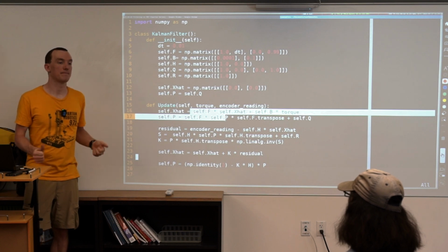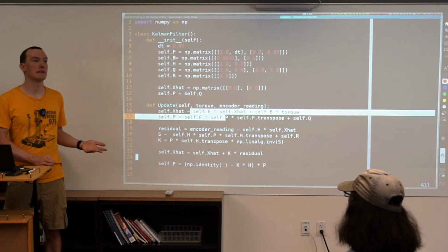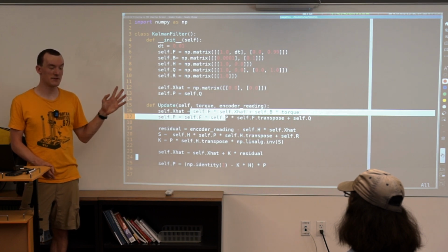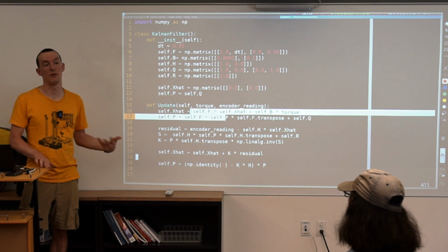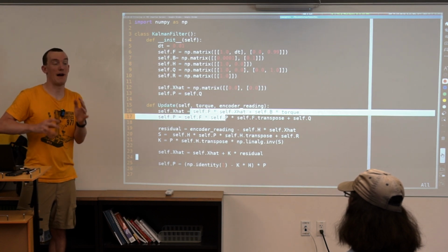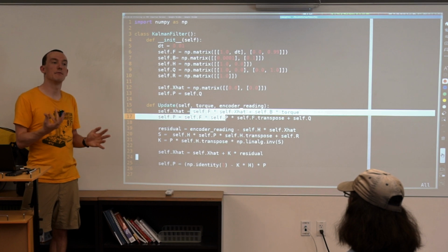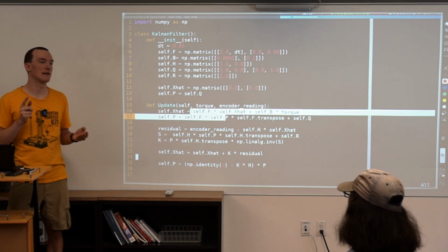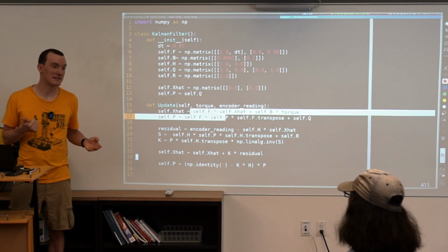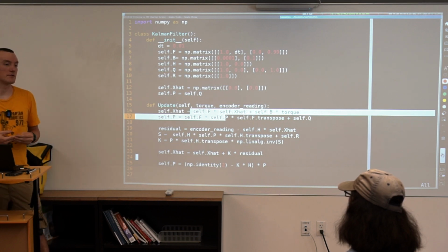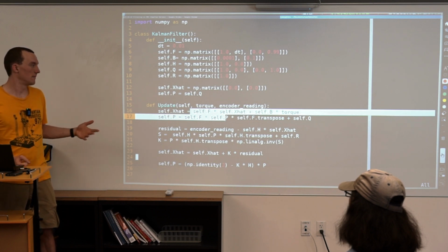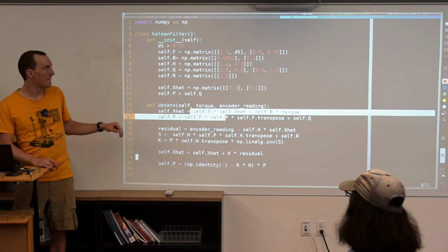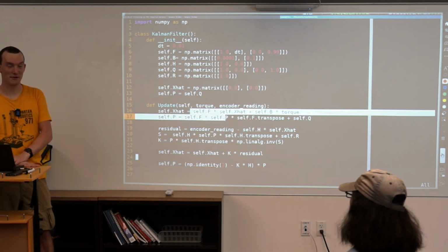I don't know. And figuring that out is system identification, and there are some open source tools for FRC that attempt to do that more automatically, where they will literally apply a voltage, look at sensor readings, and attempt to estimate what the mass of the system is, and a few other attributes, to figure out what those numbers would end up being. Using those correctly can sometimes be a bit of a pain, but they do exist. Further questions?